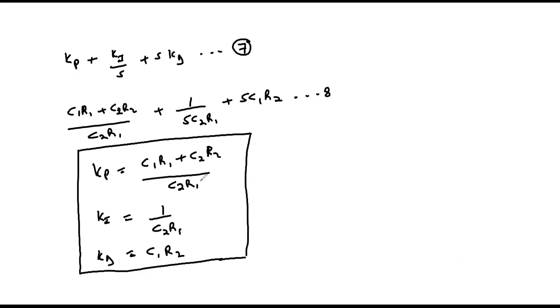And that is the implementation of PID controllers using the operational amplifier network in their inverting mode, using 2 stages of the operational amplifier network, where the first stage achieves the typical PID operation, while the second stage does the sign inversion. Otherwise, that is the end of my presentation, and thank you for watching this video.